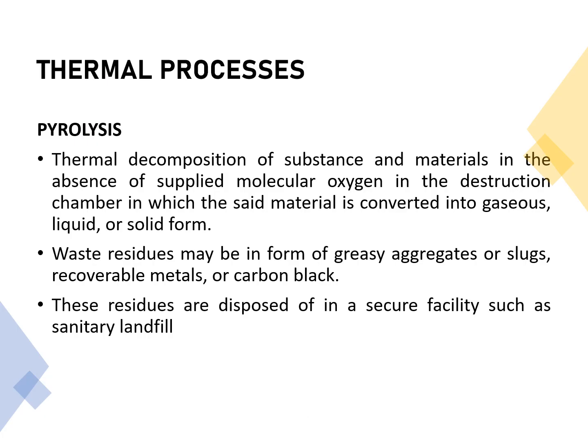So we start first with thermal processes. Under thermal processes, we have pyrolysis. This one involves the decomposition of substances and materials in the absence of supplied molecular oxygen in the destruction chamber, in which the said material is converted into gaseous, liquid, or solid form. After you have exposed your waste to pyrolysis, the waste residues may be in the form of aggregates or slugs, recoverable metals, or carbon black. These residues are disposed of in a secure facility such as your sanitary landfill.